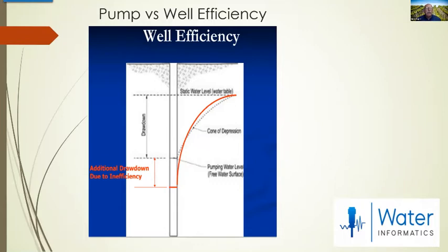And one of the things that we always used to get when we were designing the irrigation system was a pump test. Pump test is based on motor to wire efficiency, and so that pump test is a good tool to show you what the cost of your pumping requirements are, but your well efficiency is completely different.